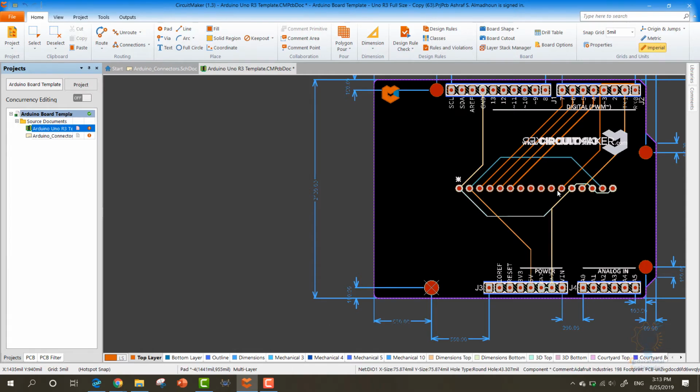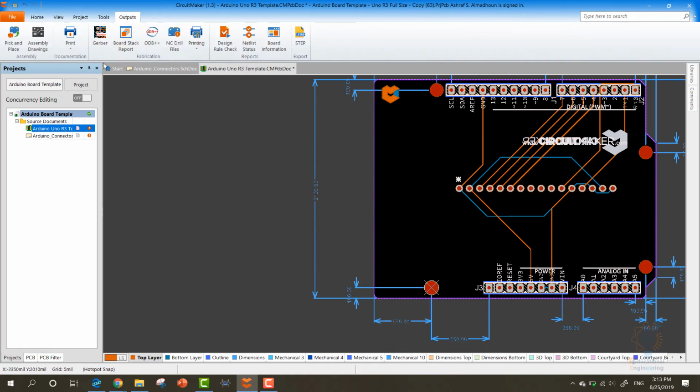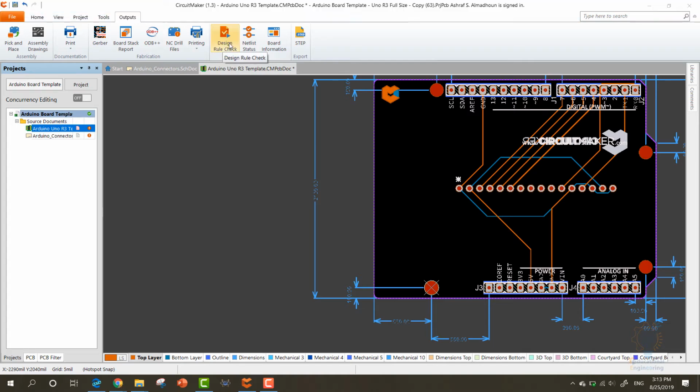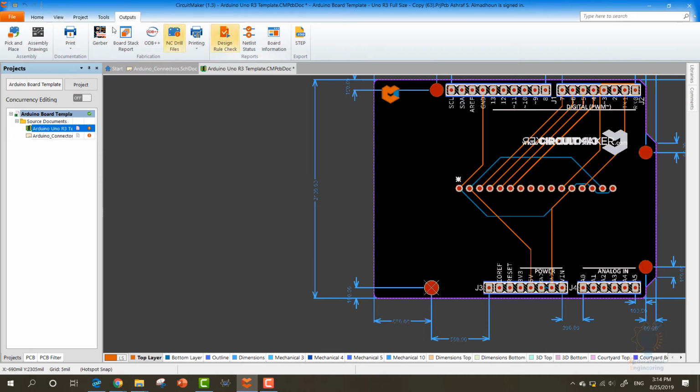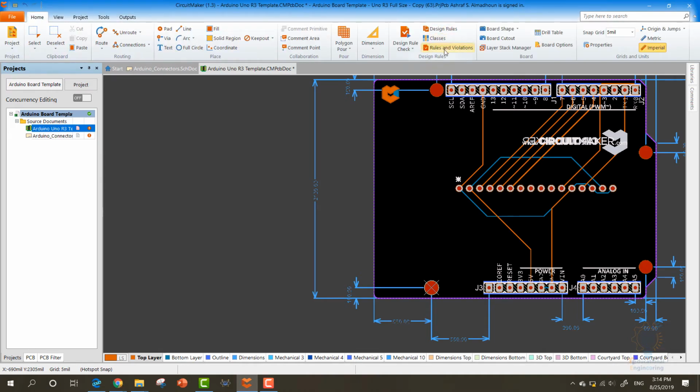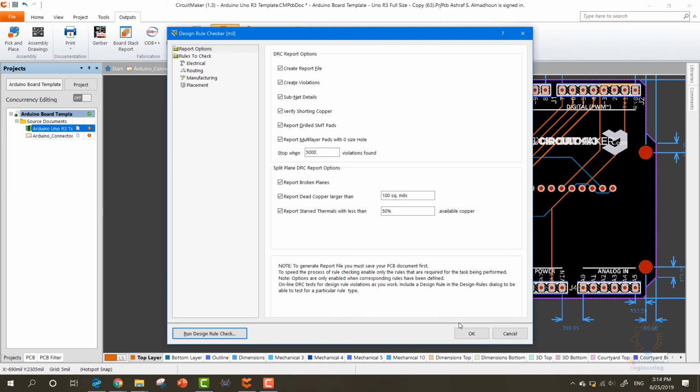And as you can see, we have the LCD module in the middle. We can click on the output and get our Gerber file, the assembly drawing, or choose the drill file. It gives you a wide collection of options. You can also do the design rule check from here, after editing the design rule options here and here if you have very specific design rules, depending on the way that you are going to use to manufacture the PCB. Now again, here the design rule check, click OK.